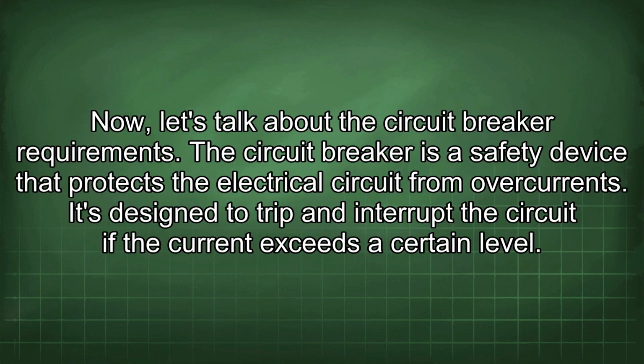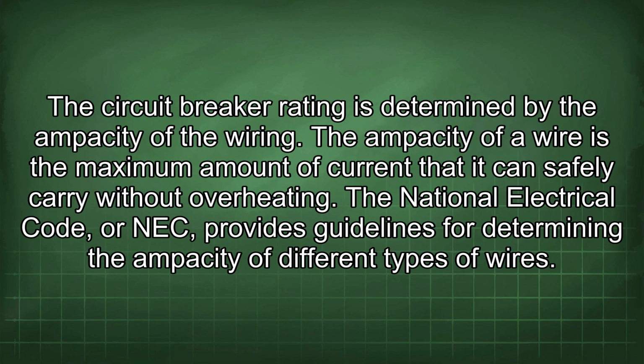Now let's talk about the circuit breaker requirements. The circuit breaker is a safety device that protects the electrical circuit from overcurrents. It's designed to trip and interrupt the circuit if the current exceeds a certain level. The circuit breaker rating is determined by the ampacity of the wiring. The ampacity of a wire is the maximum amount of current that it can safely carry without overheating.